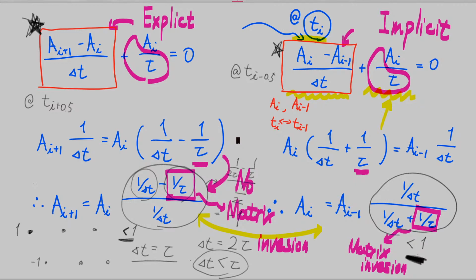So if you remember the time you spent getting the DC solution, you now realize the importance of this difference. In the case of an implicit time marching scheme, you have to make the inversion of your Jacobian matrix. And this Jacobian matrix is slightly modified by this 1 over tau, 1 over delta t term.